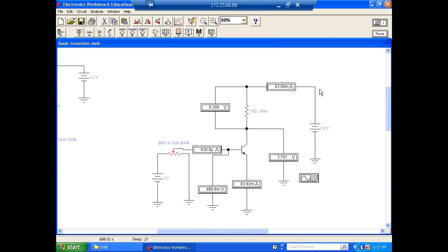But we saw all three regions. We saw the active region when it acted like a rheostat, right? We saw cutoff when we dropped it below the voltage that was required to turn it on. We had no base current. If we have no base current, then the transistor cuts off and acts like an open switch, but we still saw a little bit of collector current, way down in the microamps. Guys, you have to understand, it is not an open switch. It is not a closed switch. It's a transistor, a semiconductor that's been doped. A semiconductor will always have a little bit of resistance, and it will always have a leakage current because there is a path. If I open a switch, there is no path. But with a transistor, we always have a path for current to get through. We call those leakage currents, but they're very small.